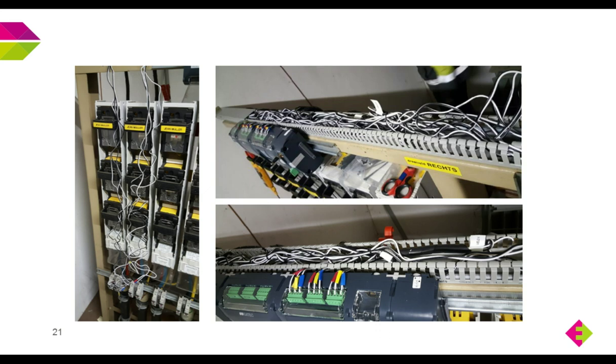You see here one installation of the measurement of the current transformers, in a low voltage installation in a substation. Mostly we have 8 cable fields. With the old current transformers, you needed 8 times 3 phases, which is 24 current transformers.